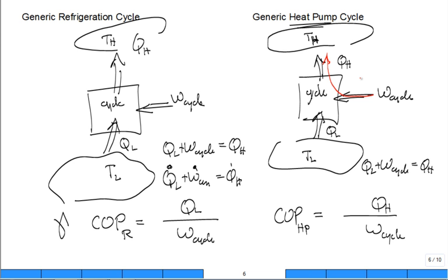But what you can do is provide maybe 1 kilojoule of energy, and grab from the outside, on a cold winter day, another 1 kilojoule of energy, and provide 2 kilojoules of energy to the home to keep it warm by only paying for 1 kilojoule of energy from CPS in the form of electric energy. If you had electric resistive heat, it's 1-to-1.